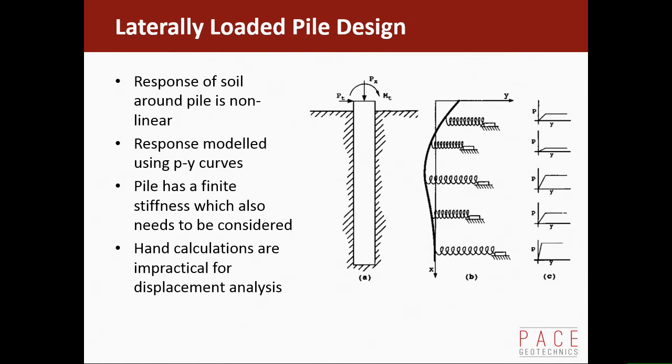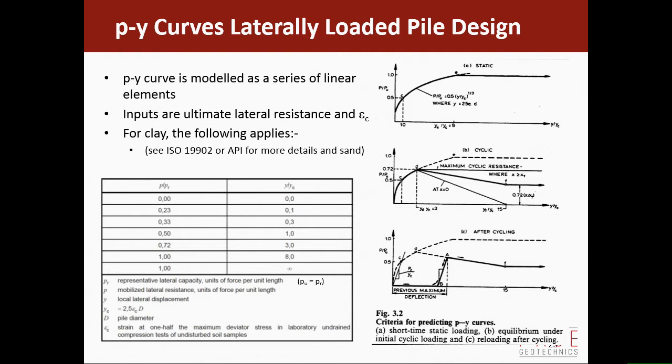Now we have what are called PY curves, which model the response of the soil, and they're curves like this, where if you just take the case of a static pile, then when you load it up initially, the response is quite stiff. It doesn't move that far. But as you increase the load, the soil starts to behave plastically around the pile, and it starts to yield more easily, and at some load, the pile will just move continuously through the soil for no increase in load. A bit like if you're cutting steel, it has a certain shear value, and it'll shear at that point, and something would pass through it. That applies to both sands and clays, a similar form of PY curve.